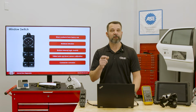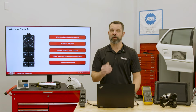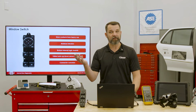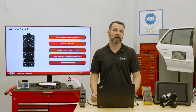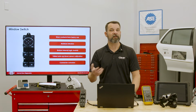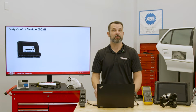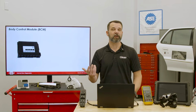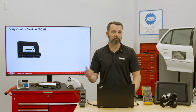We should always also inspect for any liquid damage that may be affecting either the connectors or the logic board. And if you have the ability, check for network communication faults. And you're going to find these very commonly on vehicle platforms like Ford, GM, and Mazda. So that's the switch. Let's move on to the BCM, the body control module, which is going to be that main controller for most body electrical systems.